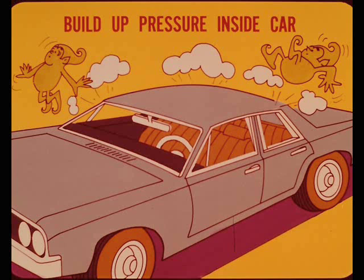The main idea here is to use the heater or air conditioner blower to build up pressure inside the car. This lets you check on the outside for air escaping around the door and window openings. Any leaks you find will help you locate holes or gaps which can cause wind noise.